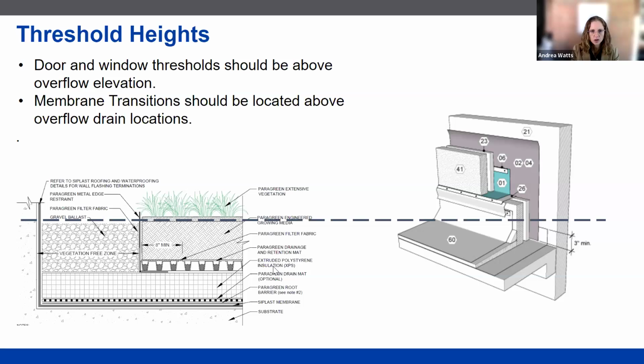If you follow that line across to our rising wall detail, you can see that in this case, we're making sure that the dotted line is falling below the point where our roof membrane ends. So where we transition to the wall membrane, our through wall flashing, all of that is happening above the point where we expect water to sit and to stay. Transitions between assemblies are the weakest point in our building regardless, due to material interfaces and trade interaction. It's important to be conscious of not putting more stress on them than is absolutely necessary.